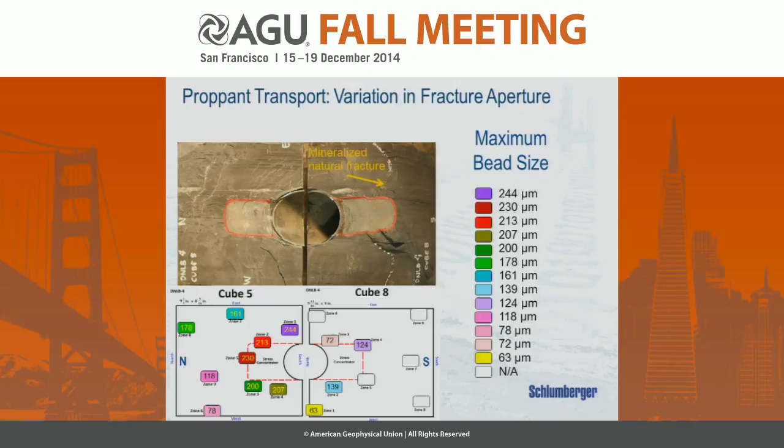And this slide shows the summary of colored beads distribution in the vicinity of the northern slot and the southern slot. I would like to remind you that the northern slot was the direction where the hydraulic fracture propagated as a one wing fracture. And we have clear evidence that near the southern slot, close to the mineralized interface, we observed no particles at all.